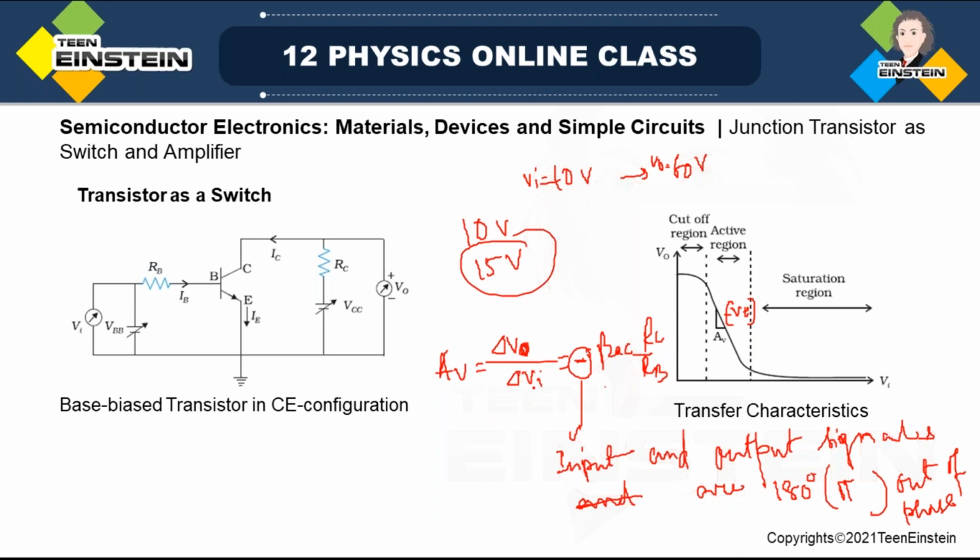If you apply a certain voltage, it will be amplified, because this ratio has the value beta AC, and beta has very large values, times RC by RB. If we just control this factor, then we can control the magnitude of the amplification, just by the external circuit, by manipulating the resistors in the collector and base junctions.